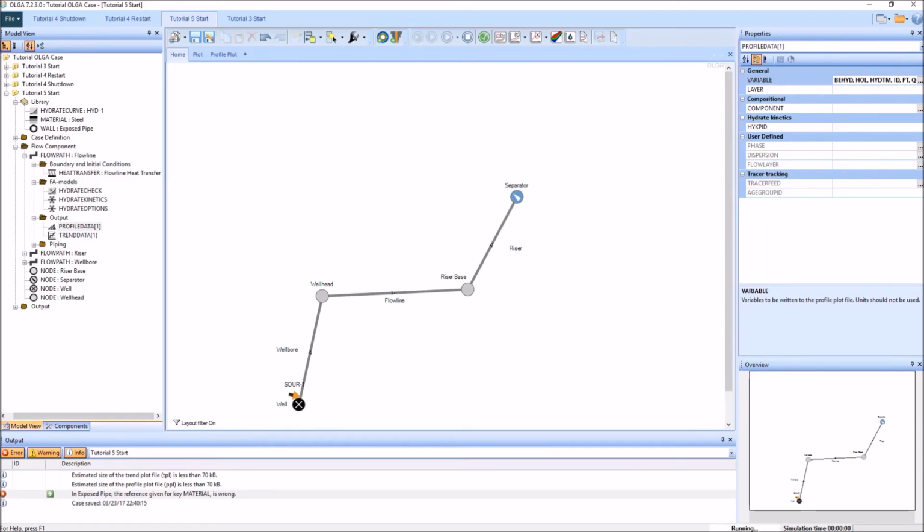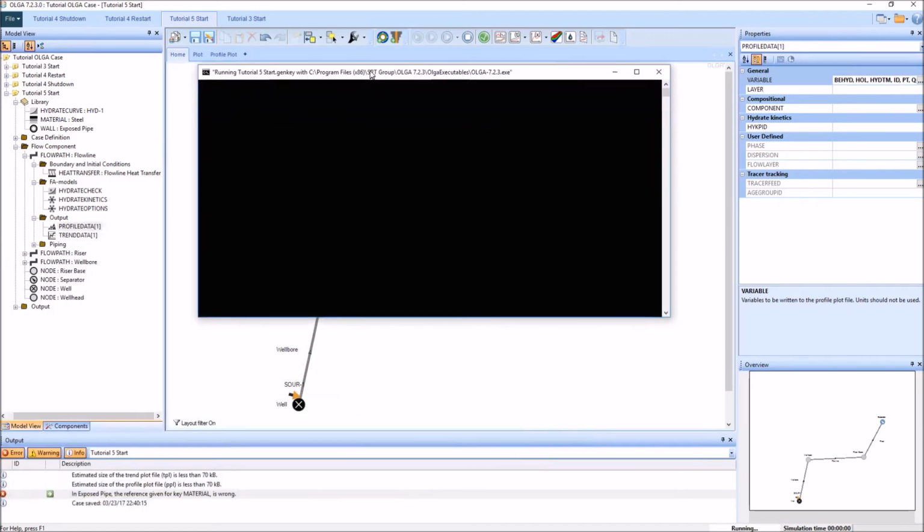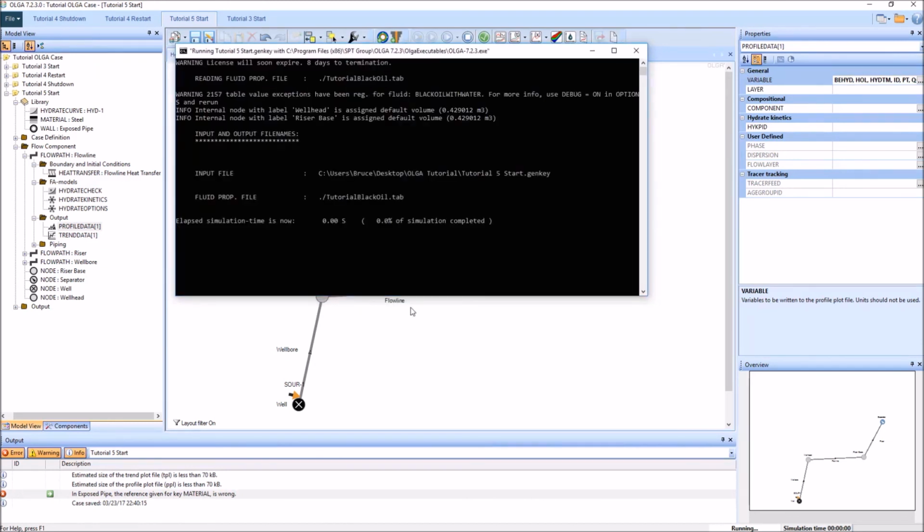and run our simulation. So this viscosity ratio, it's effectively the ratio of the slurry viscosity with hydrate formation to the base oil viscosity. So when this value is 1, then we should see nice flow without any hydrate formation. But with hydrate formation, this ratio can increase significantly. And OLGA has a hard cap of 4,000 for its viscosity ratio, or its relative viscosity, coded into it.